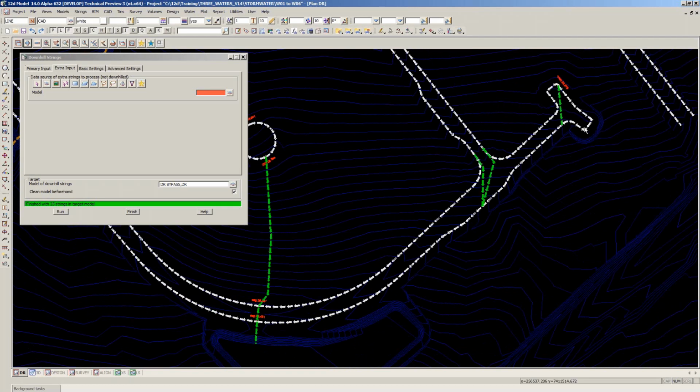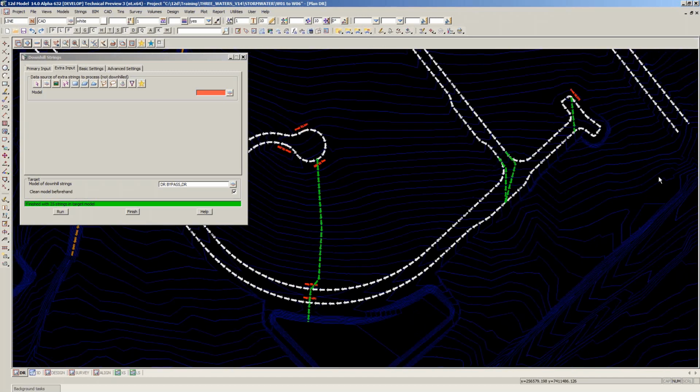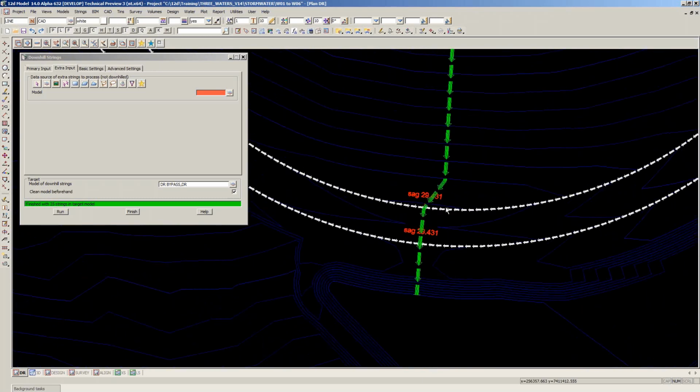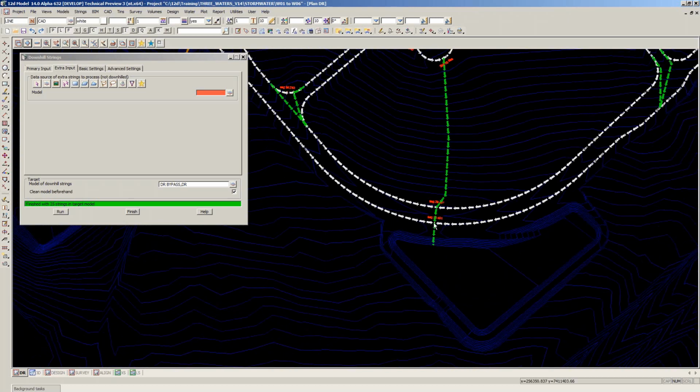Likewise, up where this hammerhead is here, I don't personally think it's worth modelling any of the channels in this hammerhead. I'm really just interested from the top of this green string, it'll sheet across the surface and then start flowing into the gutter here. So a lot of this stuff with a one-way crossfall, that's probably the trickiest thing to do here. This green string here, there's actually an easement in this job, a stormwater easement, and this would be picking up potentially interallotment drainage and a sag pit from up here, coming down to the two sag pits right down the bottom before we go into the basin.